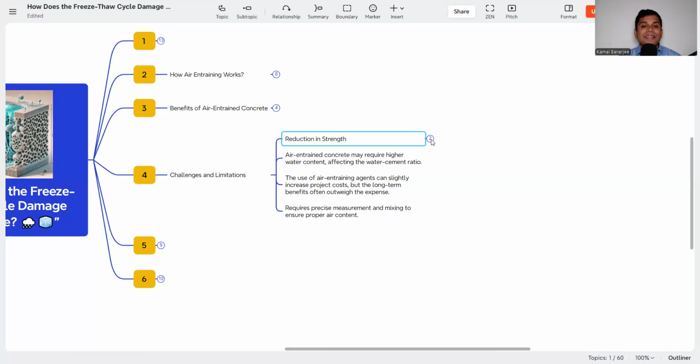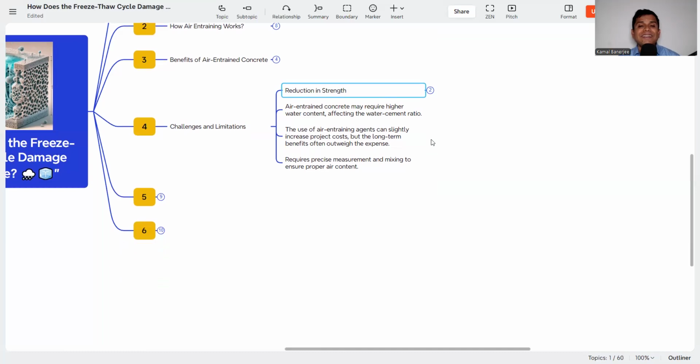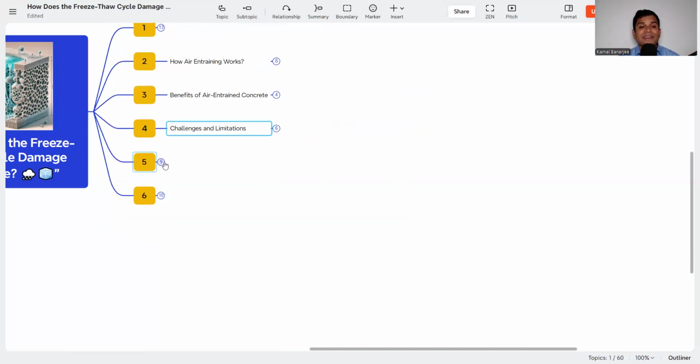Please watch. Then, the use of air entraining agents can slightly increase project cost, of course, because it's a special type of admixture, so it has a cost, but the long term benefits often outweigh it. If you are not using that, the repair cost will be more. So in that way it can be beneficial. Then it requires precise measurement and mixing to ensure proper air entrained content. So that's the quality control part. You need to mix it properly, whatever the requirement is. So these are the challenges and limitations for air entraining concrete for the Freeze-Thaw cycle.